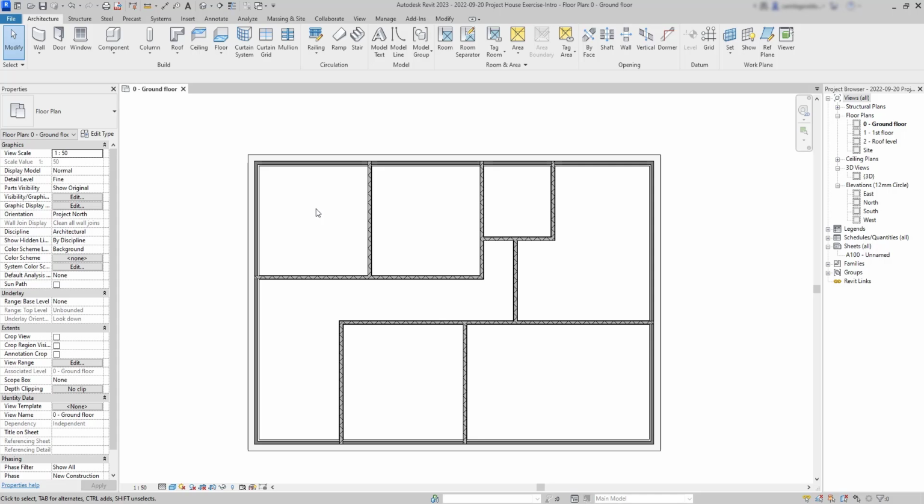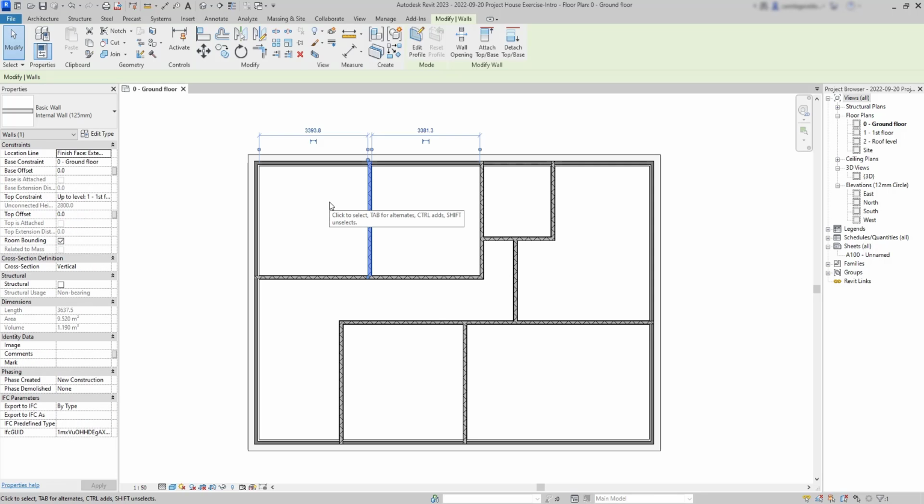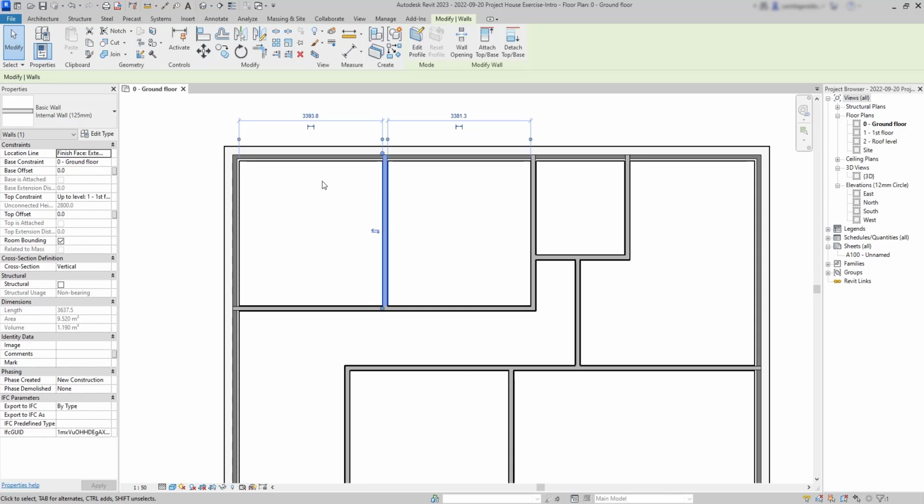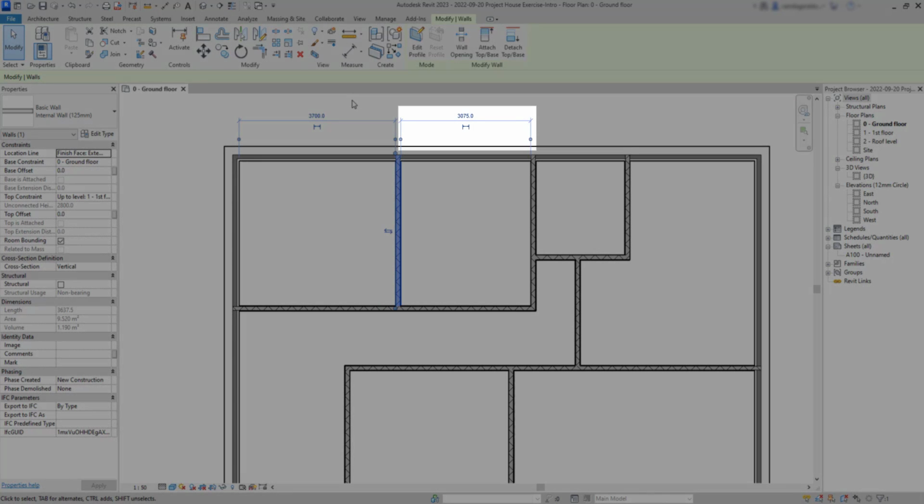Let's start from the top, at the left side, and select this wall. Now look, when you select a wall, these temporary dimensions show up on the screen. Their purpose is to indicate the distance to the nearest intersections, in case I need to move the wall to the sides. Here, this length has to be 3700 mm, and I simply click on it to edit the value. Just this, easy. Then, the next dimension also changes as the wall moved to the right.